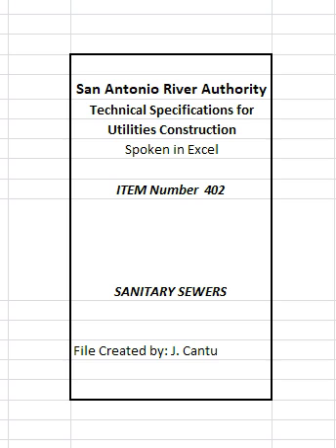No fillers or extenders shall be added to the PVC resin other than those ingredients normally required for lubrication, ultraviolet light protection, stabilization, resin modification, and pigments essential for processing, property control or coloring. The PVC sewer pipe shall have elastomeric gasket joints conforming to ASTM D3212 and gaskets to ASTM F477. Exposed ribbed open profile gravity sewer pipe will not be permitted for use as a sanitary sewer transmission line.